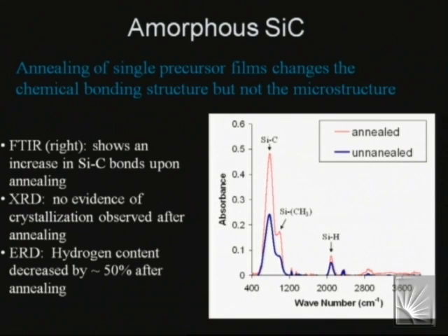We were interested in the surface characteristics of this film, and so we actually started working with, I think, Clements Berta's group to do some FTIR. This was work done by John Dew, who's now at Caltech, and he was interested in looking at the signature from an as-deposited film and a film that was annealed under conditions that would give us stress levels suitable for bulk micromachining, around 100 megapascals tensile. So you can see the data shown here.